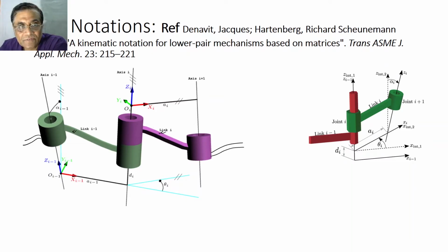Okay, here also you see this is link i minus 1. So where will be its axis of rotation? Z axis. Z axis will be at the left where it begins. Okay, and in some other books it may happen that at the end of that link you can put that axis, because it is a body coordinate frame. It hardly matters. You can put it here, here, here to describe any point on the body, but you will have to be judicious.